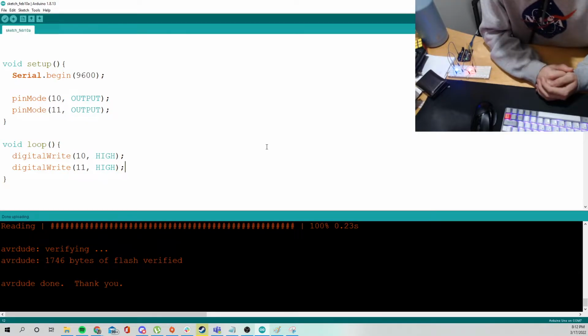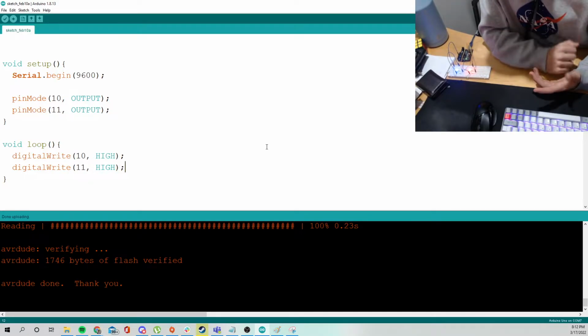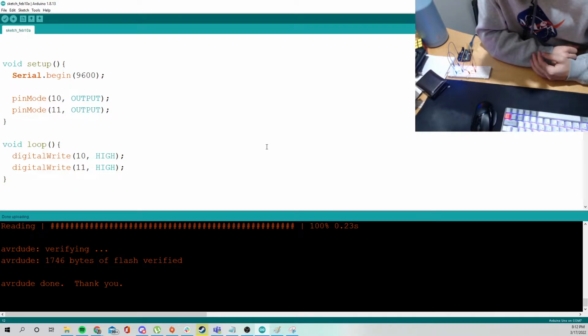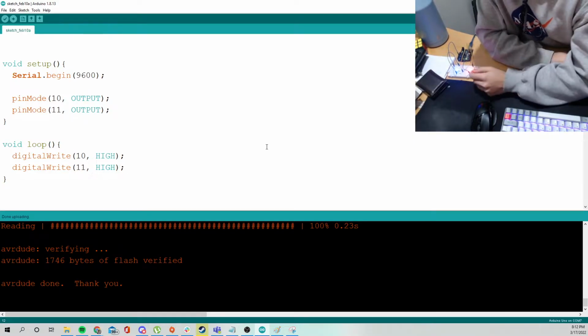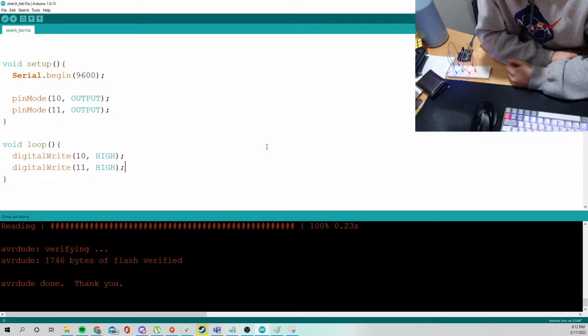If you don't have both of your LEDs lighting up, you're most likely doing something wrong with your resistor. Make sure that your connections work properly, and that your resistors are actually well connected to the metal part behind the breadboard.